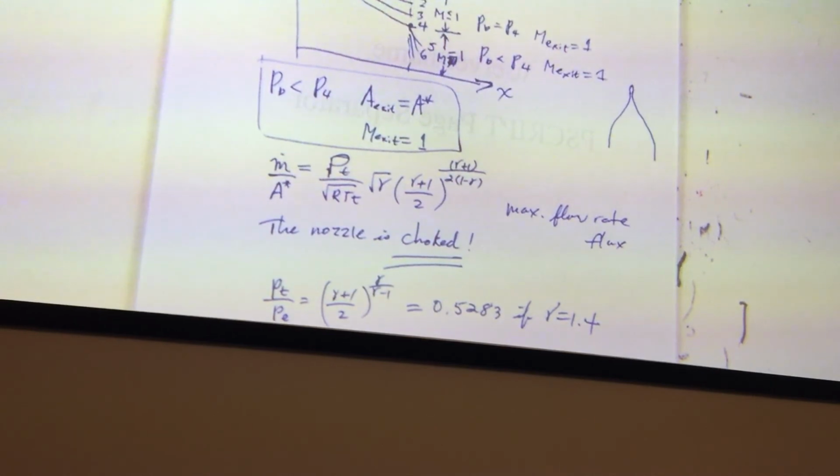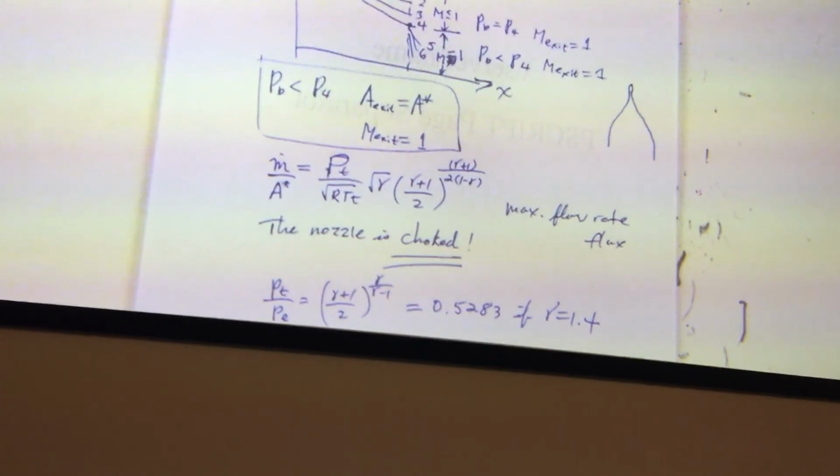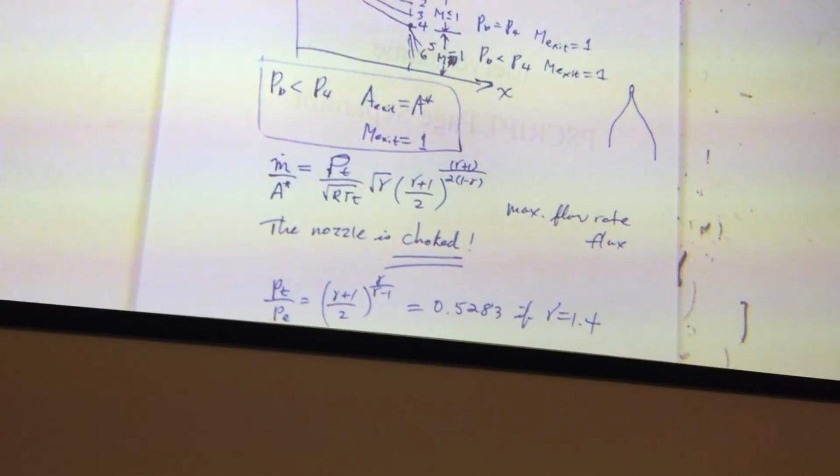So you have a lot of actuators. But usually for a space vehicle, an actuator is a penalty. Because you need to put in motors and mechanisms, and for every part of the hardware that you put in, you need to carry that many more pounds of propellant, so that many fewer pounds of payload you can carry.